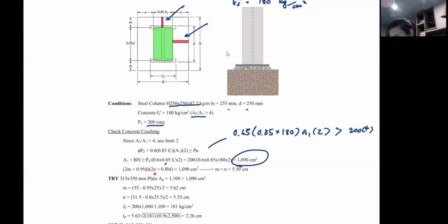Now you have to design the plate thickness based on the cantilever lengths here. If you make one way bigger than the other, you're governed by the longer one, which is not a very good engineering approach. So in the theoretical world, you should try to make these equal, so that one isn't governed by another.